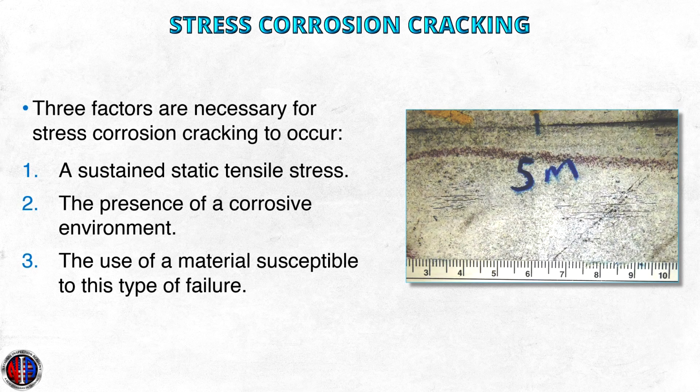In the image shown, we see stress corrosion cracking on a pipeline that was located using magnetic particle testing. For this type of magnetic particle testing, we used a white contrast background paint and visible black particles, giving us our horizontal stress corrosion cracking indications.